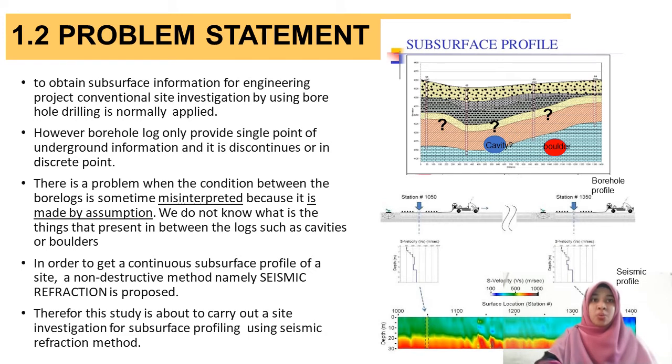We do not know what is present in between the logs, such as cavities or boulders. In order to get continuous subsurface profile of a site, a non-destructive method, namely seismic refraction, is proposed. Therefore, this study is about carrying out a site investigation for subsurface profiling using seismic method.